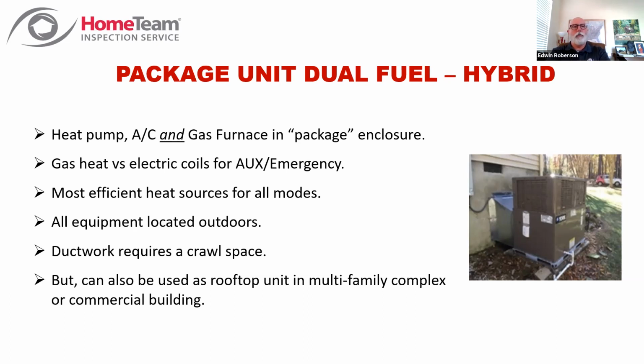But the gas heat is only used in auxiliary and emergency in the place of heat strips. And again, that's using your heat sources in the most efficient manner. When the temperature is high enough, you're using the heat pump. You get down to where the heat pump can't do its job well, and that gas furnace will kick in.